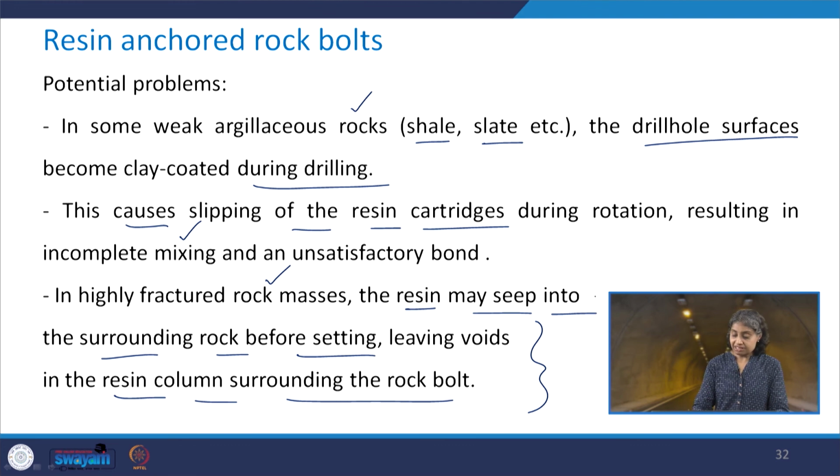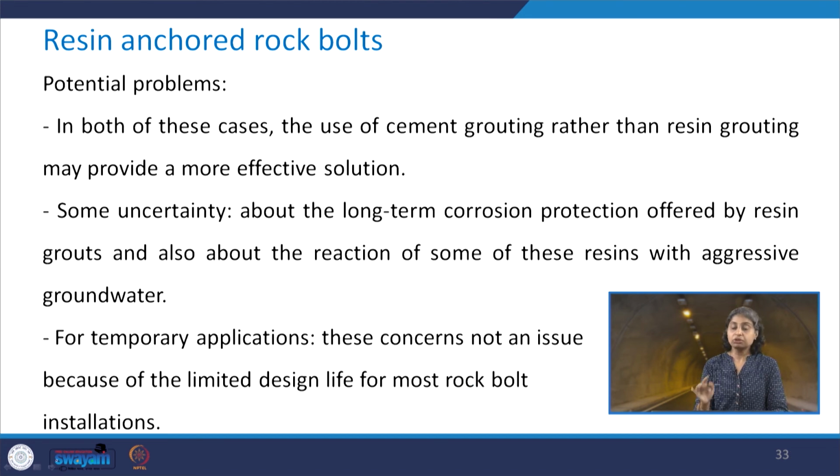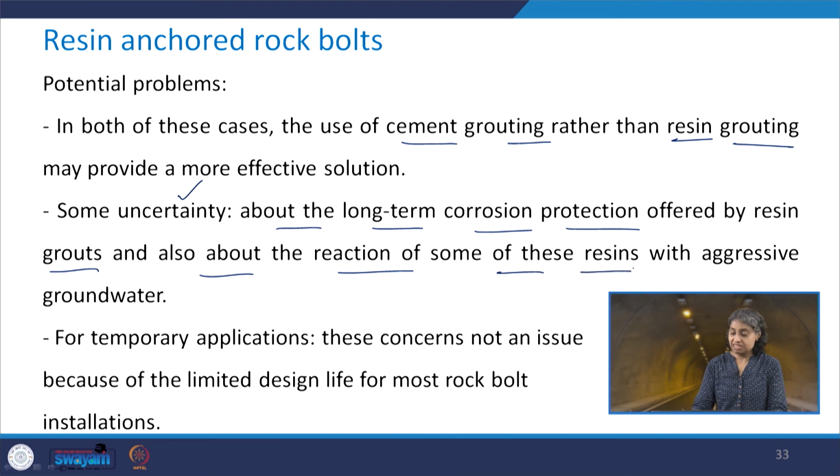Whether it is this problem in highly fractured rock mass or the slipping of resin cartridges in weak argillaceous rocks, in both cases the use of cement grouting rather than resin grouting may provide a more effective solution. Although there are some uncertainties associated with the long term corrosion protection offered by resin grouts, and with the reaction of some of these resins with aggressive groundwater.